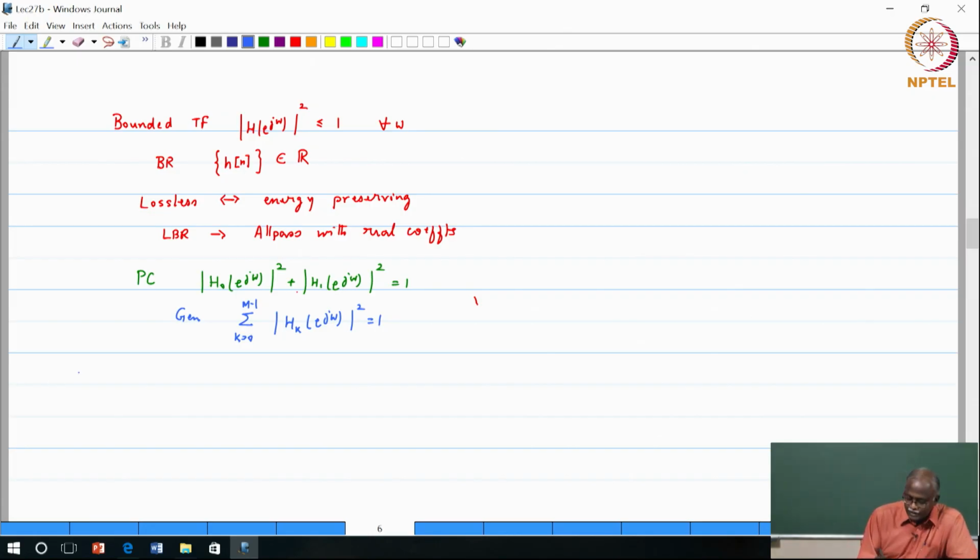The other element that is very useful for us in today's discussion is the factorization. So, the factorization, how do you visualize the zeros of a polynomial, and how do you separate them into 2 sets. So, basically yesterday we showed that if you had a transfer function H(z), which can be written as A(z) times B(z), this has n0 zeros inside the unit circle, inside mod z equal to 1.